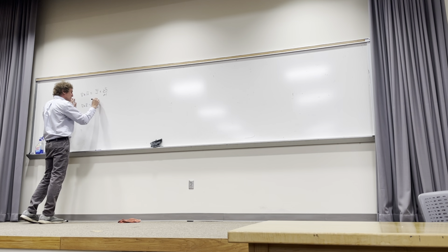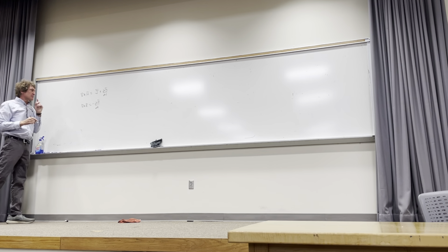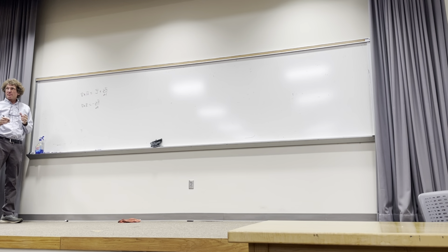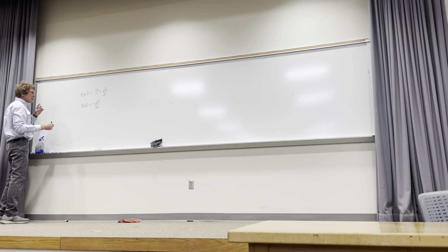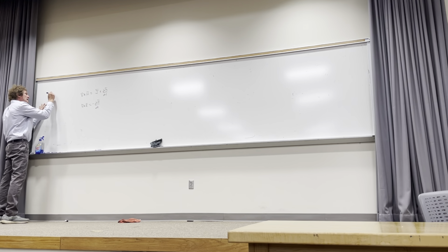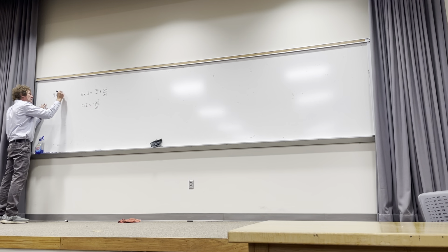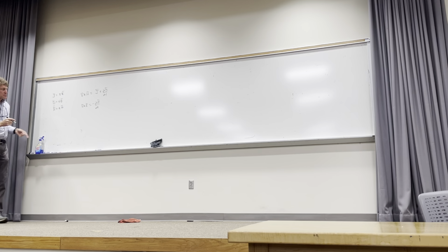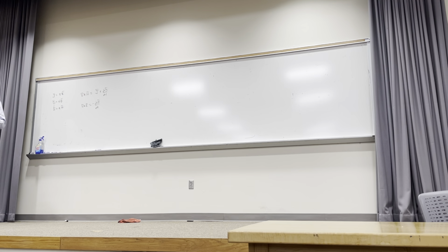Now these are probably the most basic form of Maxwell's equations. They're in the time domain, and they're spatial derivative operators of curls. The coupling is J is equal to sigma E, and D is equal to epsilon E, and B is equal to mu H. Now, sigma, epsilon, and mu have to do with the material parameters.